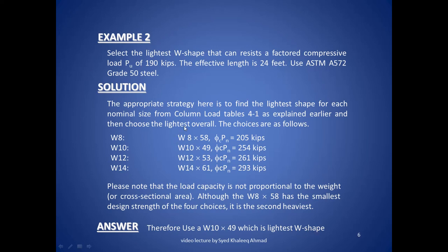Now, if there is another restriction in the question that you must use a W8 section, then you will be restricted to only this section. In that case, you will not use W10. So we have to take care of those considerations which are required due to requirements of either architecture or some other service requirements for the structure.